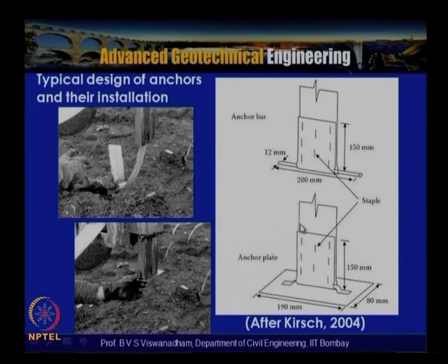In this case this is with the anchor plate arrangement, wherein the plate will be there, and there is a possibility that this anchor plate can cause more disturbance as it is being pushed into the soil, and it has the tendency of developing large smear zones. This is schematically shown in the photograph here, how the anchor plate is attached along with the PVD. So this is the anchor bar and this is the anchor plate.